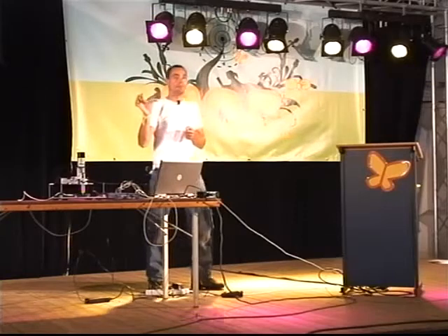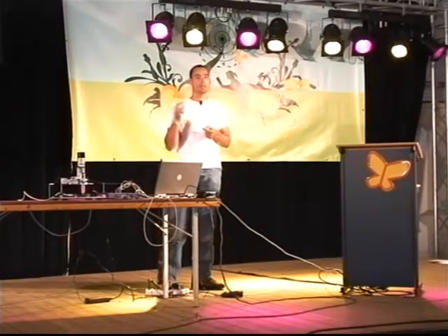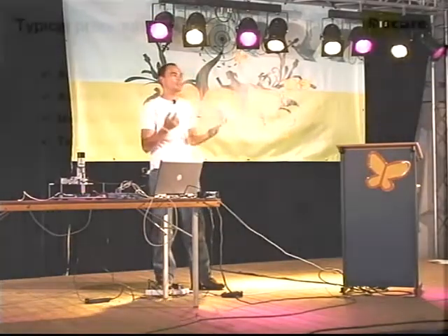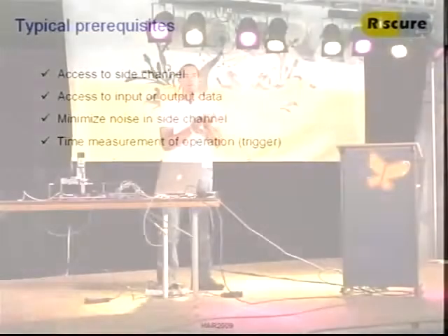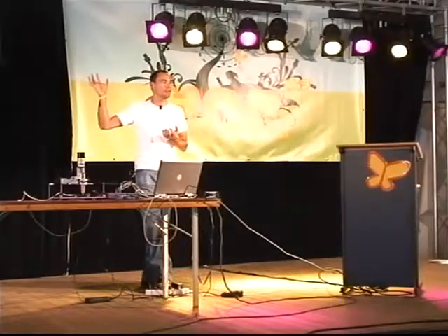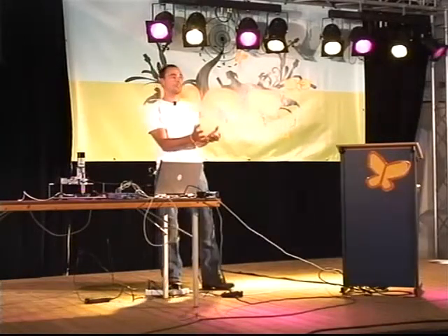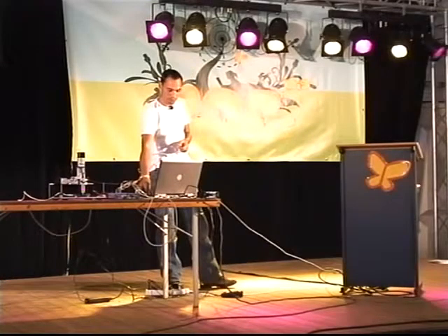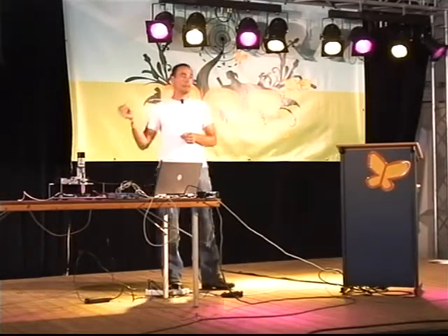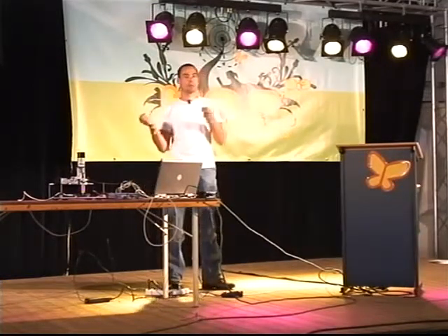You need to know what to measure. If you know that a hardware crypto operation maybe takes a microsecond, and you have an embedded device and it goes in over Ethernet or a serial cable, when does it happen, that single microsecond that you want to measure? So you need a trigger signal. And can you derive it from the design, or do you need to implement something yourself to be able to do that? And then you need to link the data to the operation that you measured.